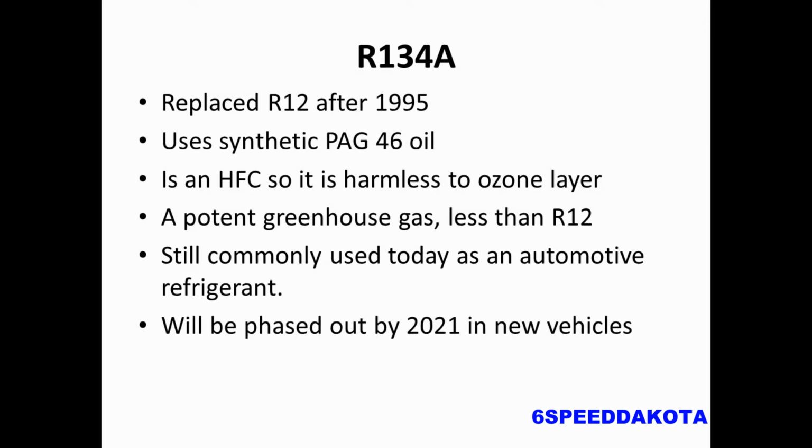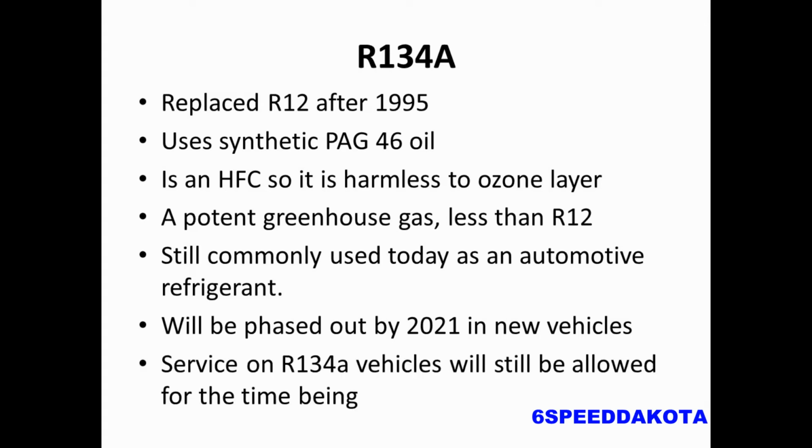Now, new regulations have caused it to be phased out by 2021 in new vehicles. But the difference, unlike R12, is that R134A vehicles will still be allowed to be serviced. This may change in the future, but as of right now, any vehicles running R134A do not have to convert to something different just yet.